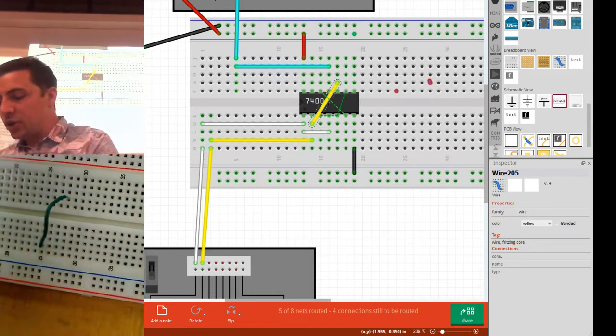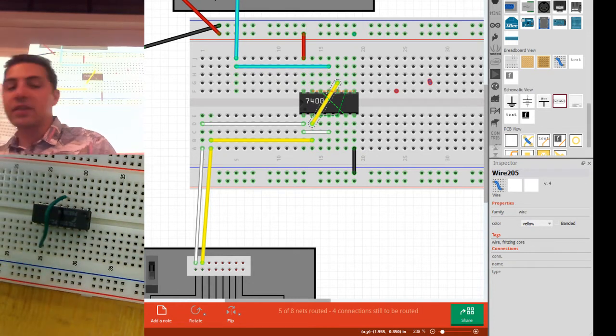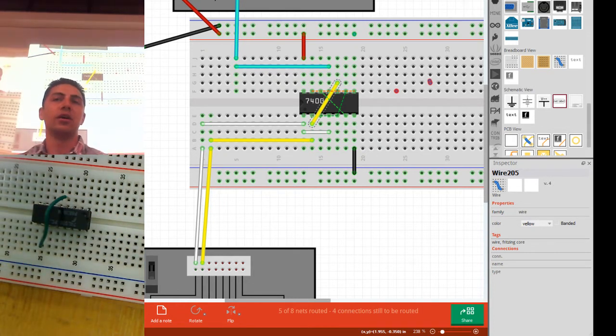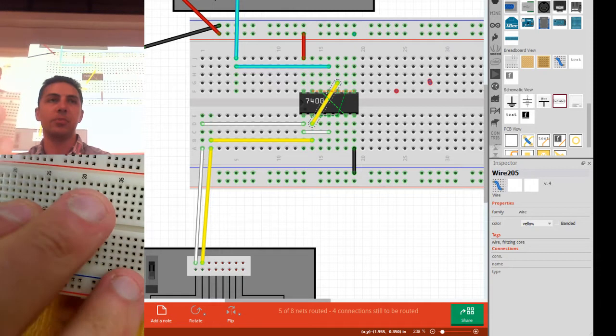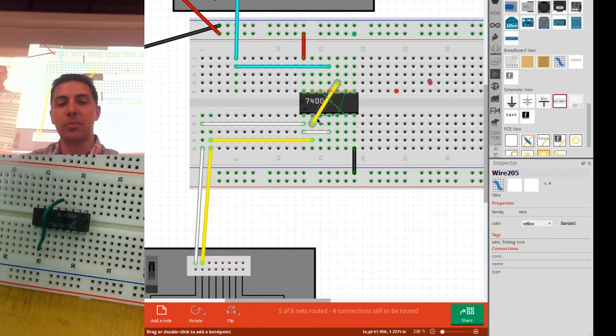And now you've got to get a new chip in and underneath it. So the rule of thumb is we never, ever will cover a chip. Okay, we just don't do it. If we do want to route a wire around like this, or across the chip, we just make a U. We just route around the chip.